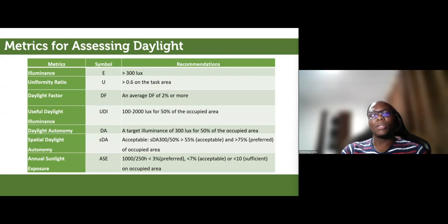The table shows illuminance-based metrics for assessing daylight quality in buildings. Historically, daylight factors and a uniform overcast sky have been used to determine the quantity of daylight available within a room. This conservative method was suited for places which have a greater proportion of overcast skies. This approach does not, however, consider the effect of direct sunlight or of varying illuminance over time.